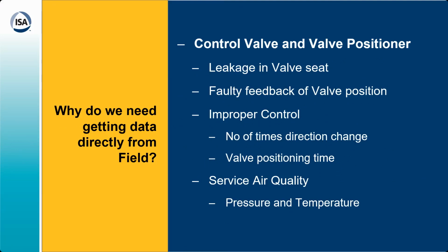So this is all available on HART on many of the valve positioners, not only the smart one which I'm talking about. Many of the valve positioners have this data, and how to use this data for plugging your leakages, that is very important to have. So we'll talk about how these technologies work.